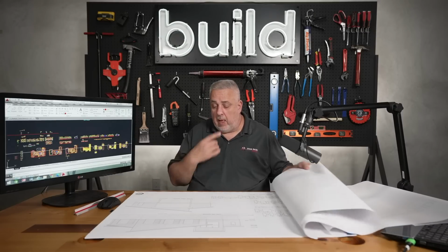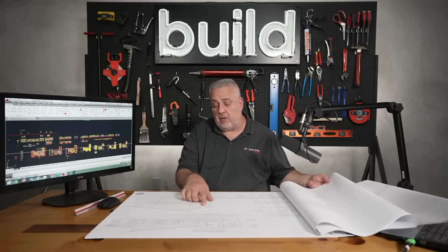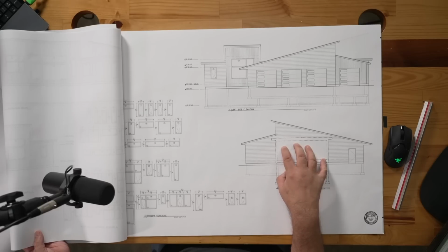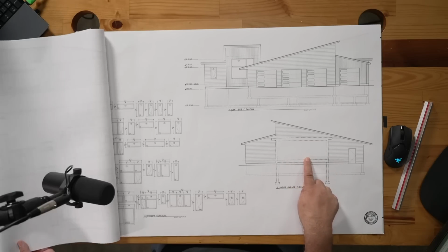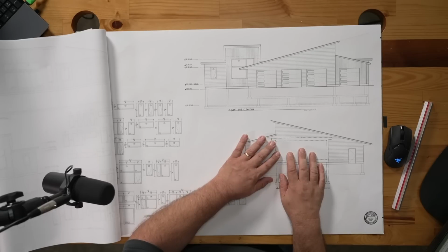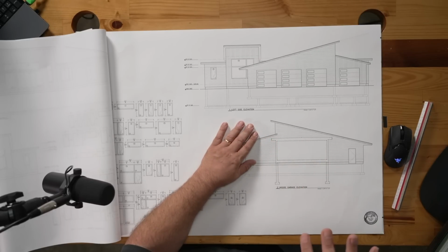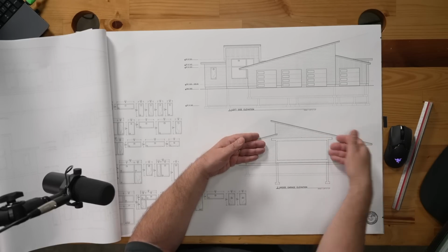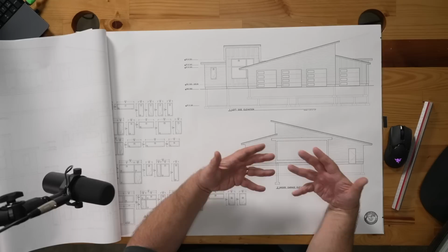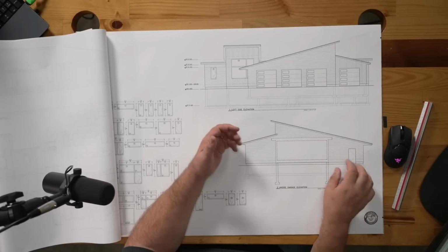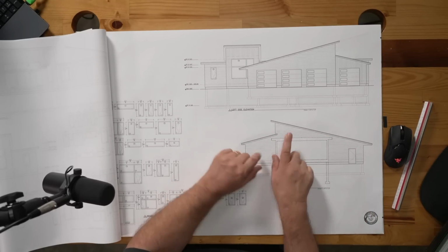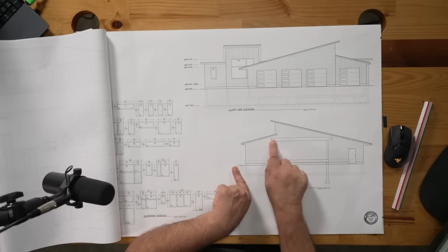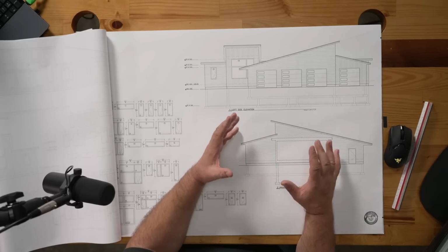More elevations. Now, this one here is pretty interesting. This is an elevation where we actually have a section of the building that is perpendicular to it, right? So this part of the elevation doesn't really exist. That part of the elevation is way out here in the foreground. So I dash in the section, but it's these other hidden elevation points happening behind what's in front that are important. So we needed to show the door, the cladding type, and how the roofs work, making sure that this sloped roof isn't in conflict with the flat roof, and making sure that a lot of these things are worked out.